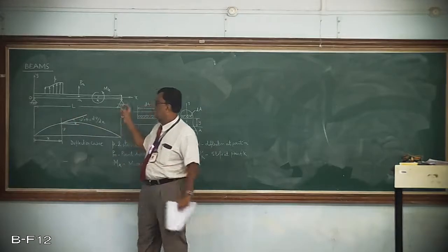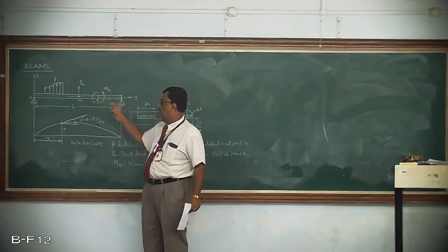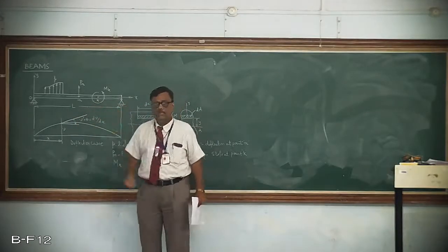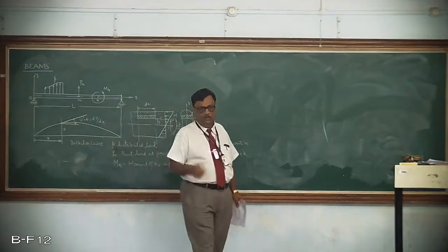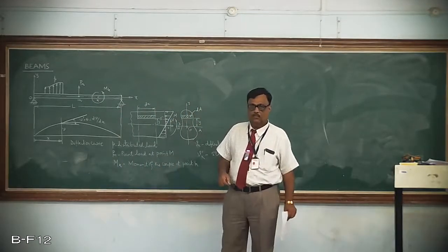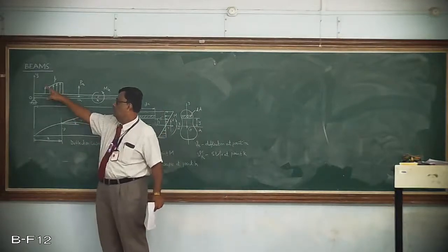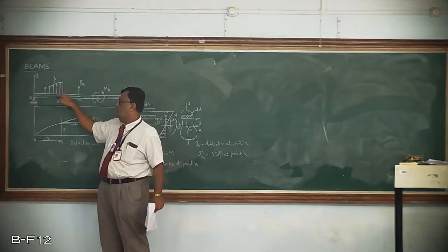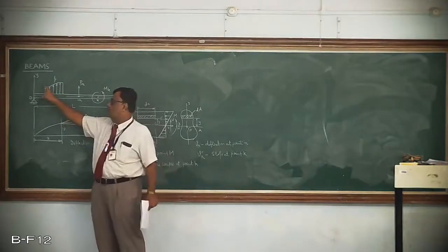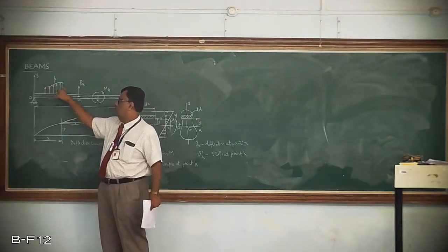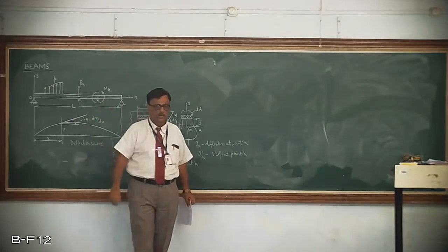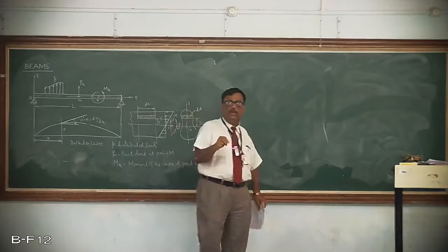See, this figure shows you a long beam supported with two supports, and these beams are supporting various types of transverse loads. The first type of load you can call a distributed load. See, this distribution is not uniform in this figure, but when the arrow's height is the same, from here to here, if the distribution is equal, then we call it a uniformly distributed load.